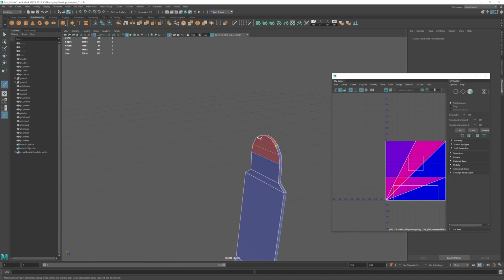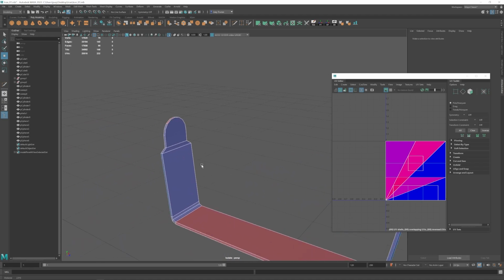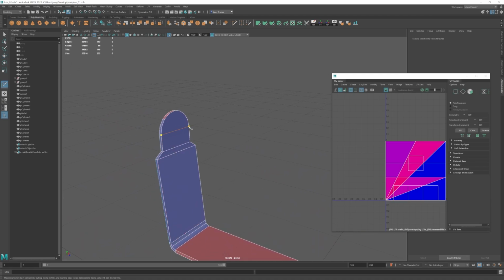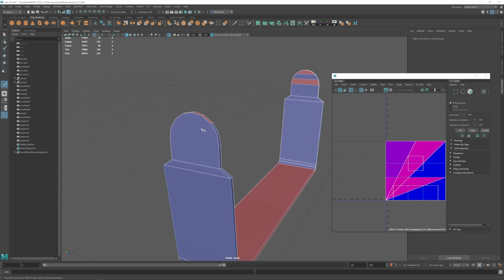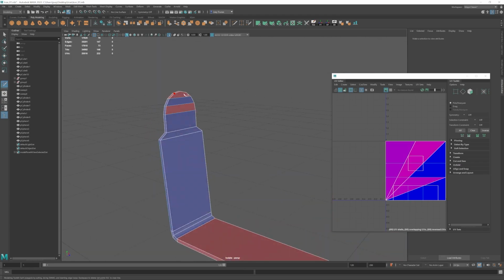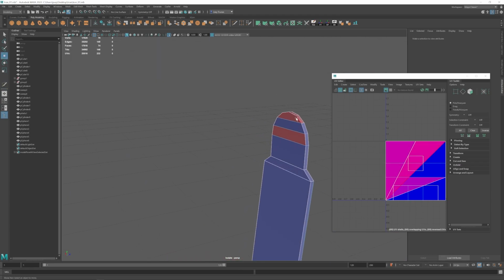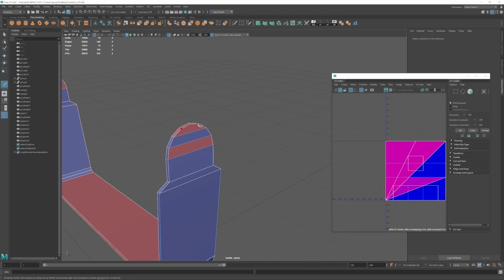So I can start off with doing a camera-based projection to remove all those cuts. I can use my 3D cut and sew UV tool to start creating cuts wherever I need them, usually along edges. And then I can go to my UV editor, highlight those shells, Control U to unfold, Control L to lay them out, and then I can change the rotation of those shells so they're nice and straight, and then I can start positioning those later on once we're done all of the UVing.